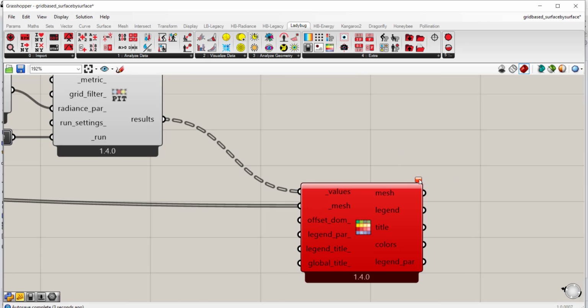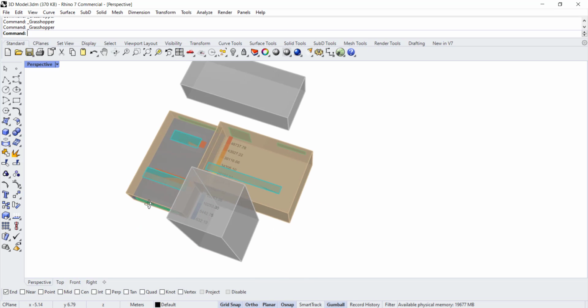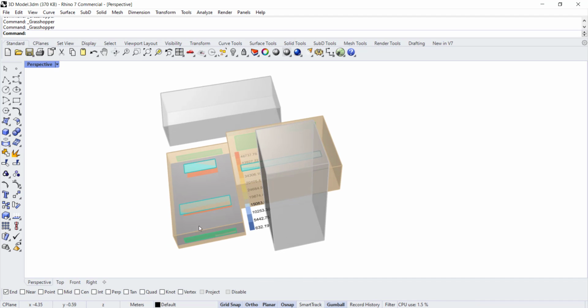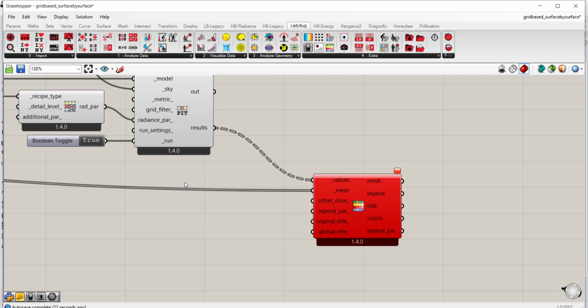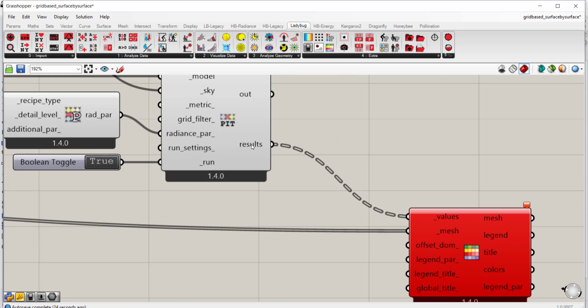And as I had indicated, here's our error. The reason why we're seeing an error is because we have 2 rooms. So if I go back to Rhino, you'll see we have 2 rooms and not all the values are applying correctly. So there's 2 things we need to do here. We need to go back to our Rhino, to our Grasshopper, and we're actually going to flatten the results. What that requires is to right-click and flatten.